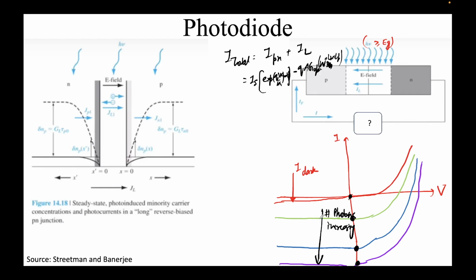However, on the reverse bias side, we can appreciate it much better, because the majority, in fact a heavy majority of the contribution will be coming only due to the presence of light, not due to the contribution from the reverse saturation current or this exponential term, because it's negligible here. That's why we operate the photodiodes in the so-called third quadrant over here. We apply this as a reverse bias.